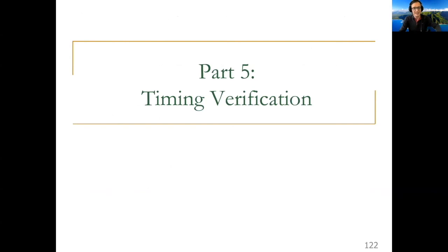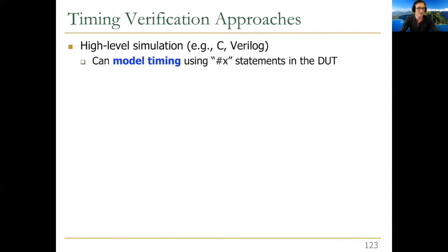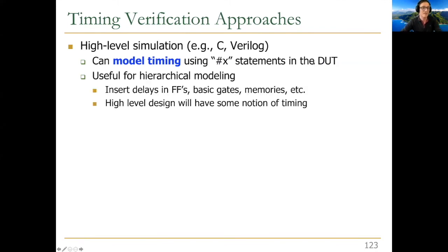Okay, let me quickly cover timing verification. We're not going to go into much detail on this, and then we're going to conclude. Basically, there are multiple approaches to timing verification as well. You can do high-level simulation, like Verilog. You can model timing using the statements that we saw in the design under test, like the timing statements. It's useful for hierarchical modeling, clearly, and high-level simulation. You can insert delays in flip-flops, gates, memories, anything basically you want, including wires, as we saw earlier. And high-level design will have some notion of timing in this case.